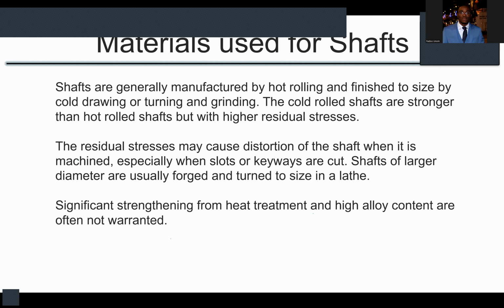When you finish, you can carry out turning operations to make sure the cross-sectional area is perfectly circular, and then you can grind the surface to smoothen it. But when you cold draw steel, because of the forces used, stresses are developed inside the shaft